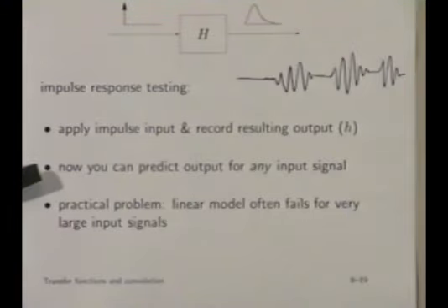But it's a very interesting fact that if you set off high explosives in the ground and measure the vibration at another place, a kilometer away. Once you do that, someone says, yeah, but what if I had not set off a high explosive? What if in fact an earthquake with a displacement motion with this waveform had acted at that point and not a high explosive blast? What would the output have been? You can now compute it, and you compute it by convolution. Or if you like, by multiplying Laplace transforms. Your choice, these are the same things. So this is not obvious stuff. Not at all obvious.